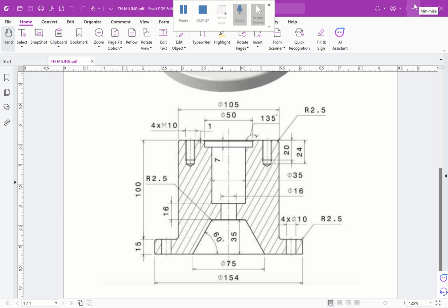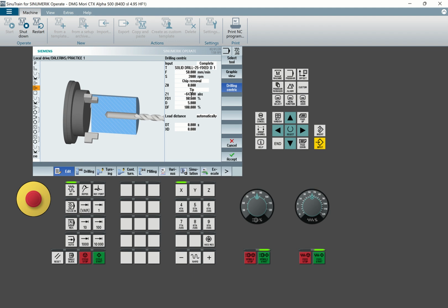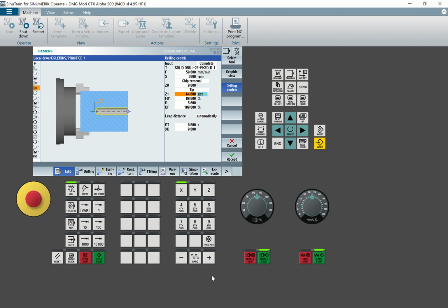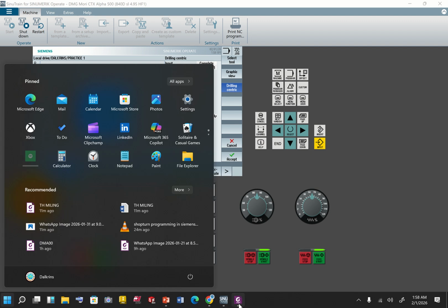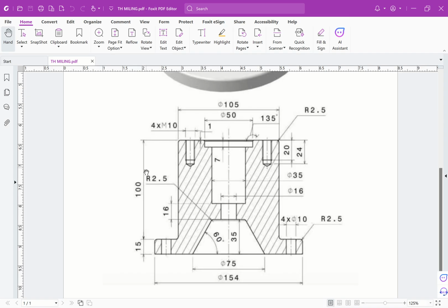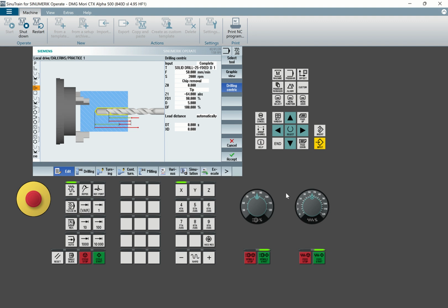Then for the main material I'll do what you call internal boring or turning. I went to minus 64. So how do I get 64? From here you can see it's 115. So 115 minus 15 will get close to 65, but it doesn't go all the way. So I want it to come to almost somewhere here, not all of it.